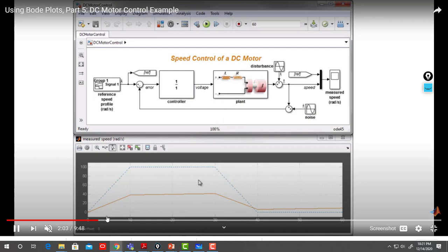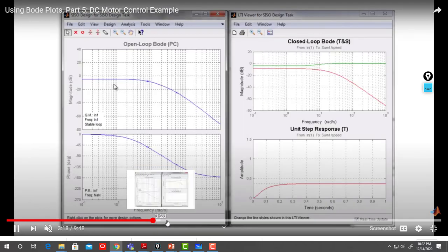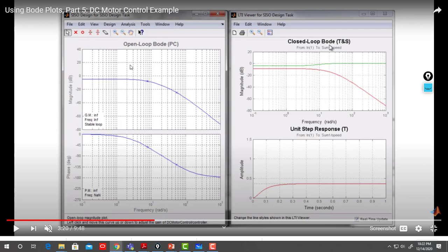So then what they are doing here, see they are showing you in the plot the open loop transfer function, that's the open loop without adding a controller. So then he will start adding a controller. He's showing you also the complementary sensitivity and the sensitivity matrix to see the performance, and the time response also to check your requirement that you have in frequency and in time domain.